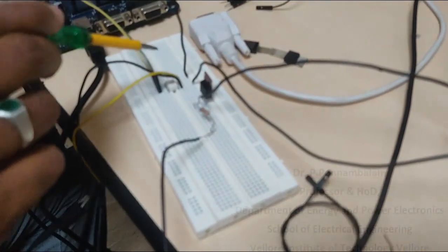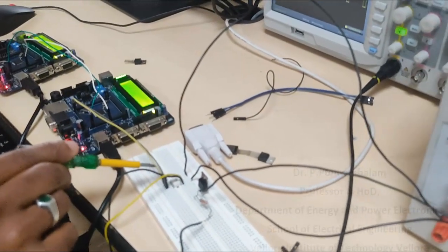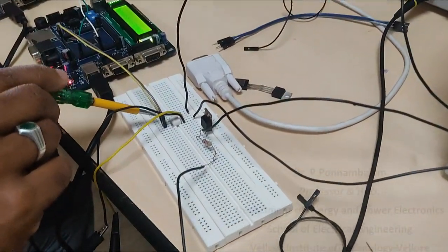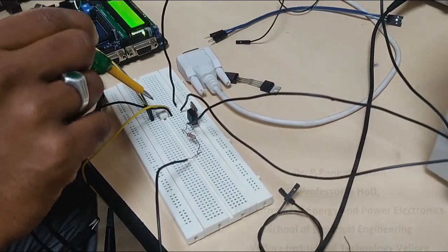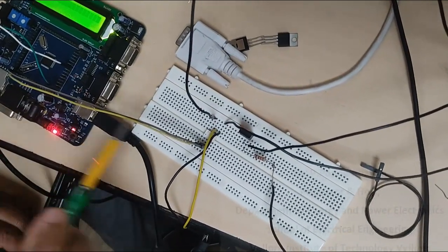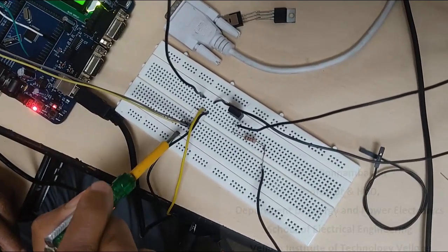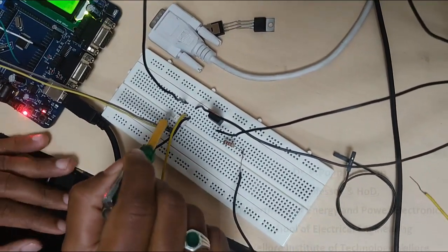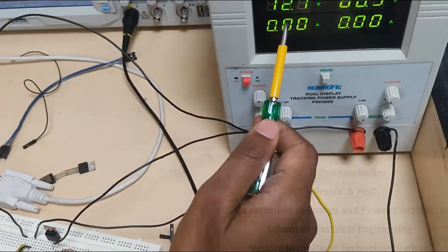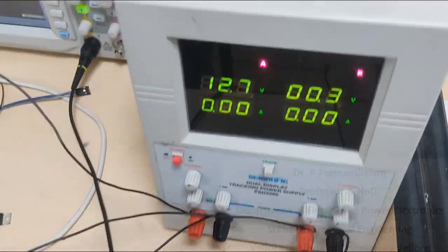Now we have connected this optocoupler. You can see from the third pin of J2 of the receiver microcontroller, I have connected to the second pin of the optocoupler TLP350. The second pin of J2, that is ground, I am connecting to the third pin of the optocoupler, and the optocoupler's 8th pin I have connected to 12 volt. I mean 12.7 or 13, we can give it 13 volt, and the negative I have connected to the 5th pin of TLP350.